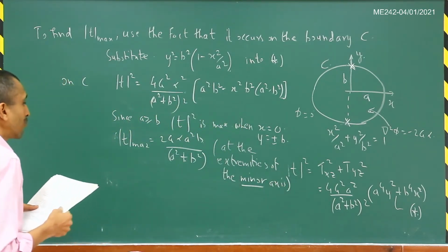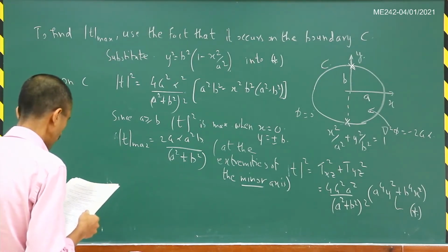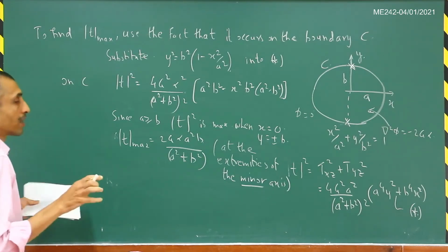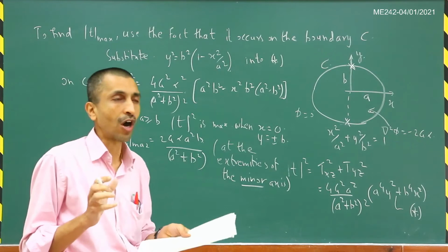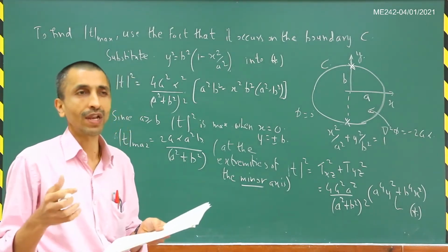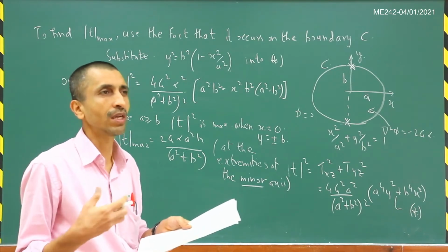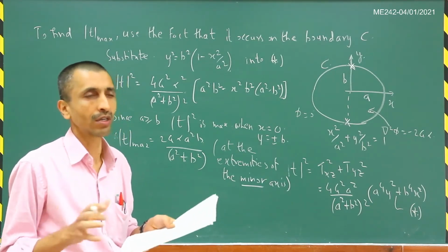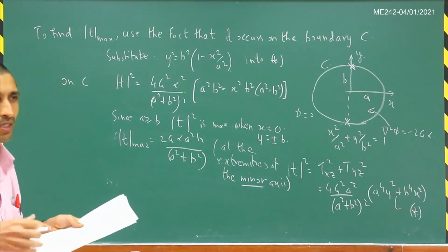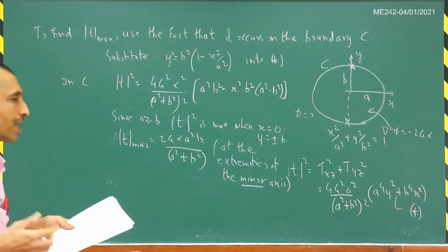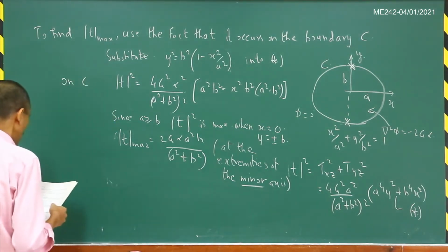Okay. Then we can find out what the torsional rigidity is also. So let us find that. Torsional rigidity is also very important, right? Because that gives a measure of how much angular deflection will occur for a given torque. And we want the angular deflection to be small for a given torque. So we will always design our cross section so that this torsional rigidity is more. So that is why finding this torsional rigidity is very important.